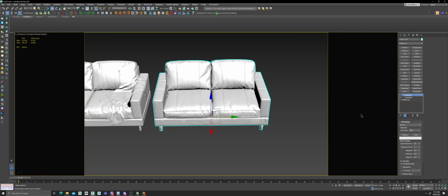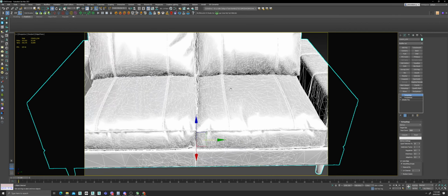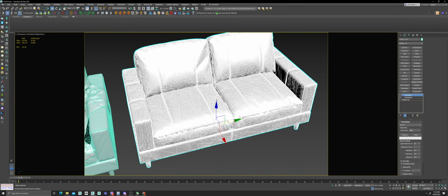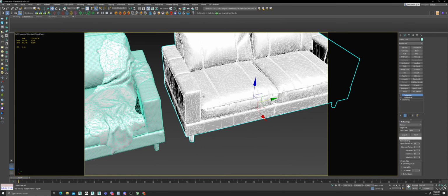So the retopology tool is a very helpful tool in fixing topology like this. Ideally, you want this to be all quads, just like this. So we can fix this, but still retain this number of vertices. Using the retopology tool, you have 3 algorithms: Reform, Quadriflow, or Instant Mesh.